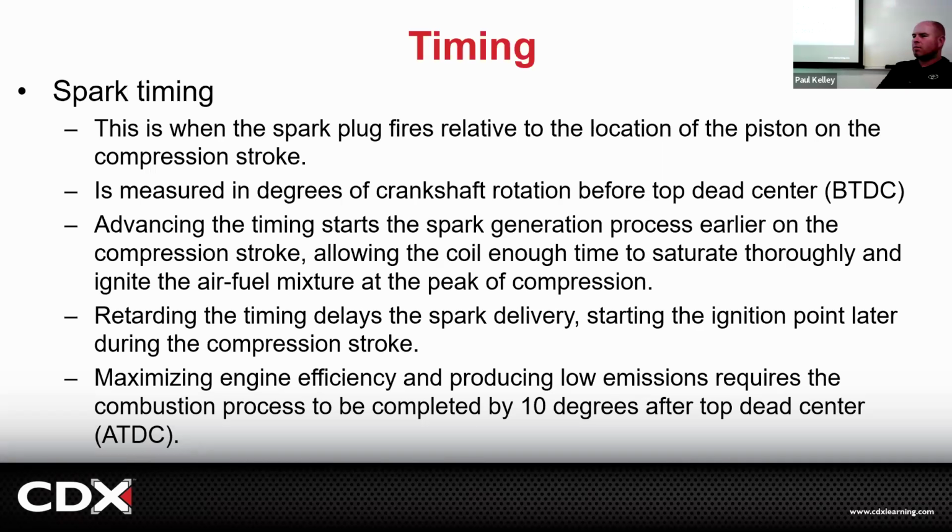It's only so long before your rod bearing's like, you know what? I'm done with this. So you might ruin that engine if you advance the timing too much. But if you don't advance it enough, you're losing power, your fuel economy is bad and your emissions are up. So it's a fine-tuned control.